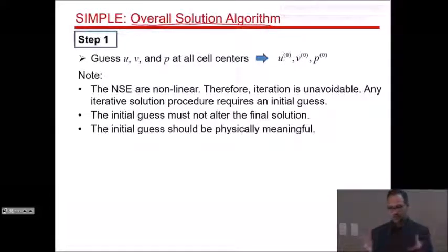Because when you start a problem, let's say you have a complex three-dimensional flow problem, you have no idea what the pressure field is going to look like. So no point trying to guess it. Sure, if it's a channel flow, you say my pressure is a linear profile for starters, for a guess. That's fine, but most of the time you'll have no idea what the pressure field will look like. So the safest thing to do is to start with uniform pressure.